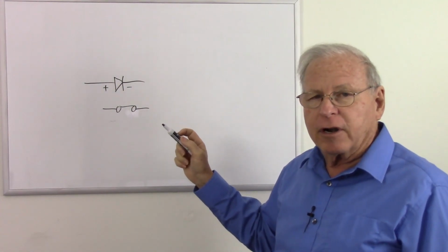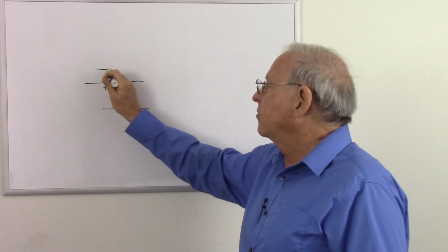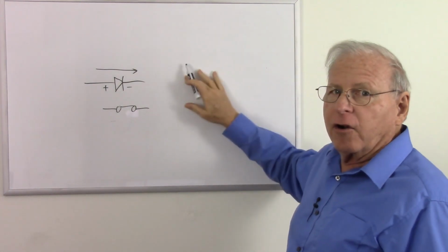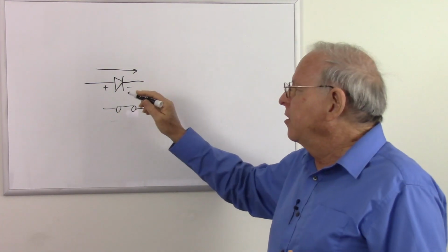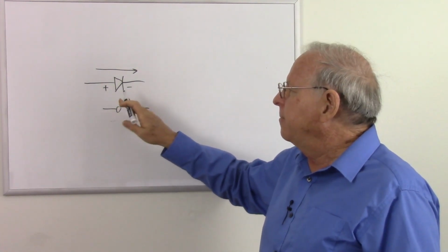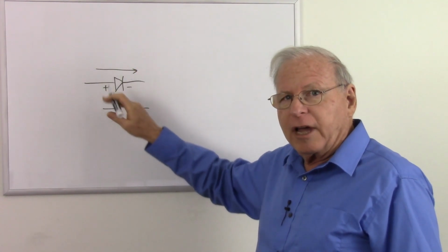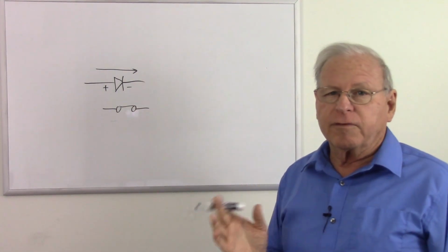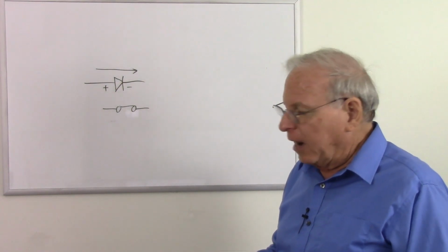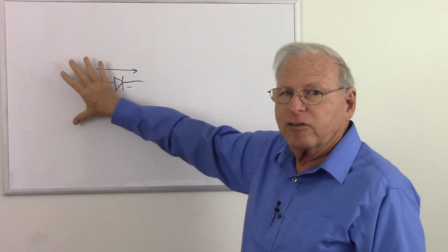Of course, we have power diodes that can handle a high amount of current. Consequently, they get deeper into that curve where we get more voltage across them. I've seen them rated around 1.5 volts. They might get up to 3 volts maybe, but typically our small signal diodes stay around 0.7 of a volt if they're a silicon diode. So that's your typical small signal or power diode, pretty much just an extension of what I've already said.